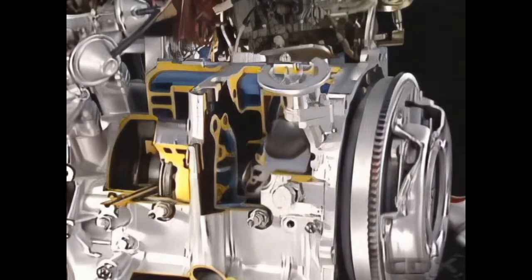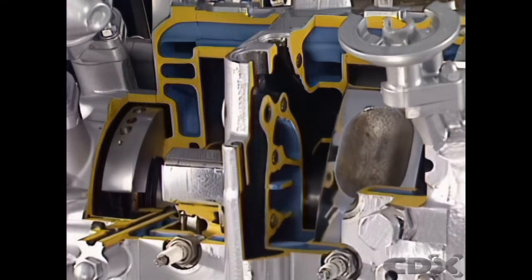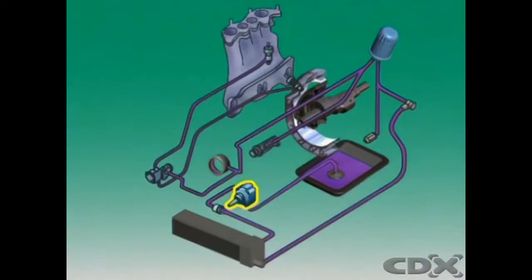The rotary engine lubrication system is similar to that of a four-stroke petrol engine. An oil pump picks up oil from the oil pan through a strainer and delivers it to an oil cooler on the front of the engine. The oil cools, then enters the oil filter at the rear of the engine. A regulator valve controls the oil pressure in the system. The oil goes onto the main bearings and rotor bearings and is sprayed into rotor cavities. Along the way, it absorbs heat, then returns to the oil pan.